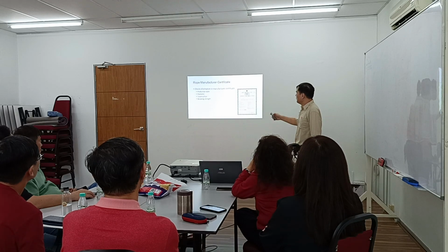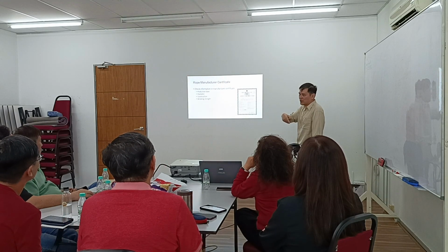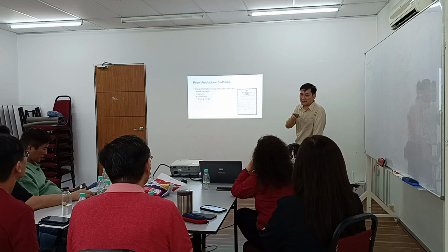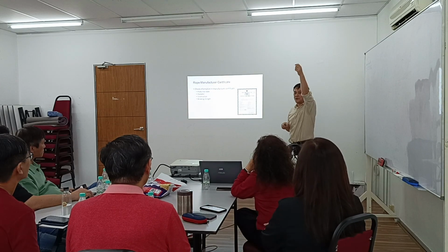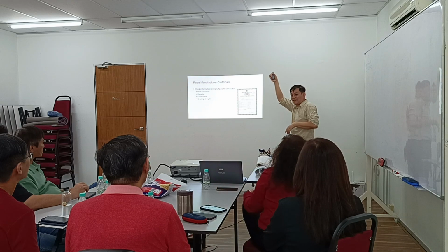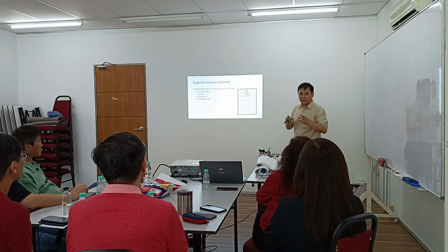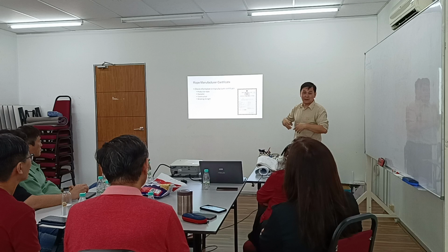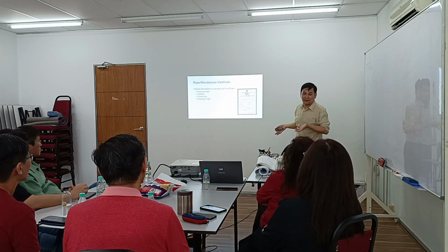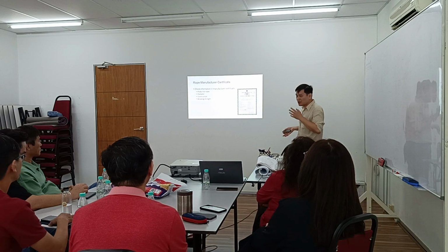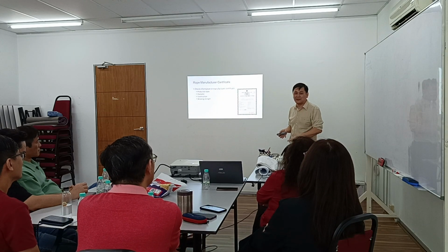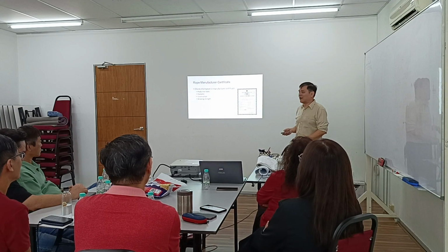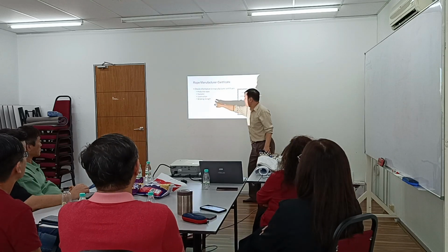So the rope manufacturer certificate, I think this is something we always have to refer to. The law says the ropes for one machine must have the same characteristics. That means you cannot have one rope from one manufacturer and another rope from another manufacturer. The best is that all the ropes are from the same drum, because then you can guarantee the same characteristics. Why do we want them from the same drum? Because we want to ensure that they have equal tensile strength, you see, breaking strength.